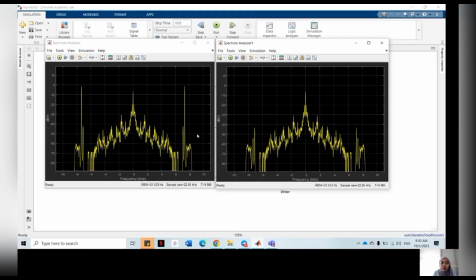from the result of this assignment Simulink, we can see the before and after output of using the notch filter. We can see that it suppresses the noise at a specific frequency. So from the frequency -6 and 6 kHz, it is being cut off or removed from the sound wave.